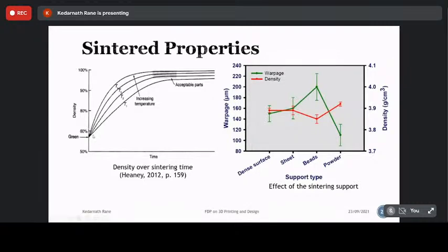Why? Because as you see in our volumetric mixing, we are considering the optimum volumetric loading at this point, right? So the other constituents, the non-metallic constituents, typically binders and polymers, are involved. That's why the green density is low as compared to the sintered density.